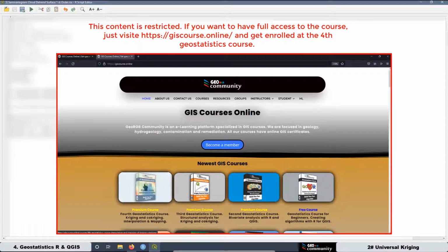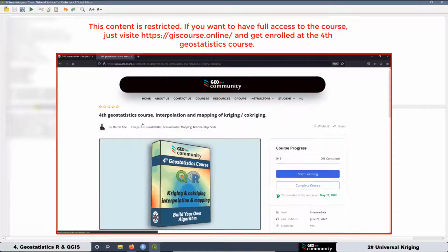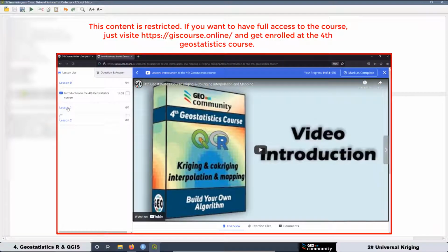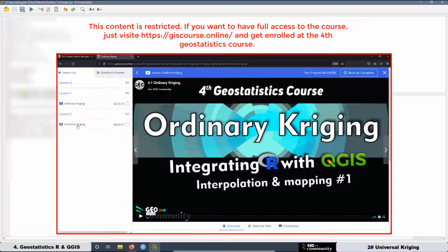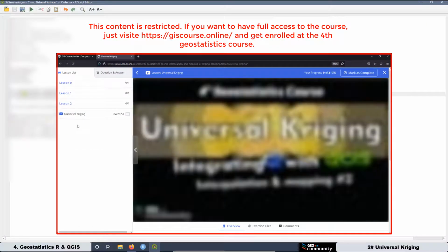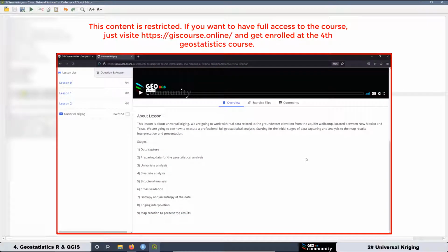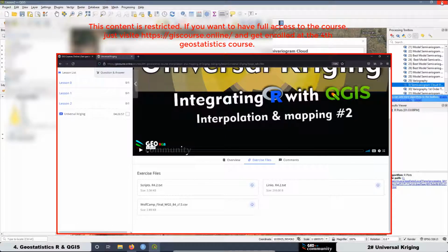As you can see in this formula, what we are doing is assuming that the dependent variable, that is the groundwater elevation, depends on x and y. And with this formula, the software R is going to remove the trend from the data and provide us the omnidirectional semivariogram cloud for the residuals after removing the first order trend surface. Okay, this one is the first order trend surface. And let's see what happens then.